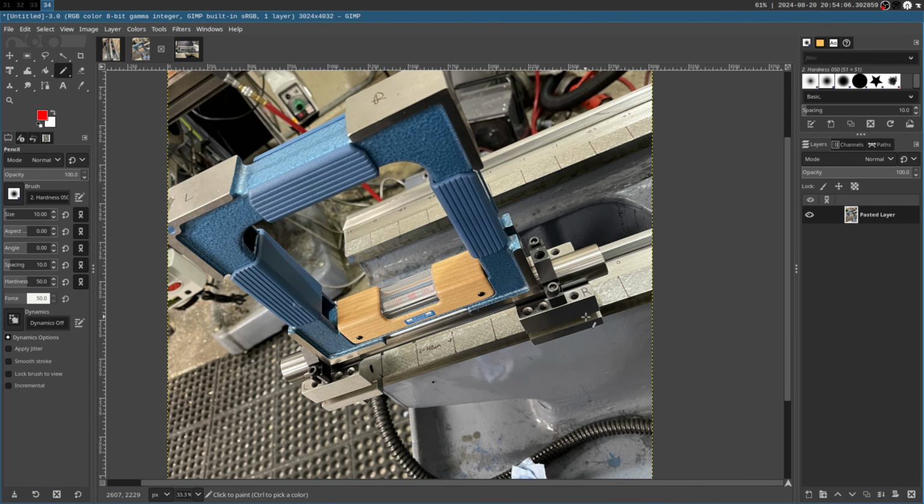Okay, anyway, so this is the little dumbbell that I built, and then what I do is I take the dumbbell and I set the level on top of it. You can see that I've denoted the left and right of the dumbbell and of the level. This makes sure that even if there is slope in the dumbbell, let's say this side was lower than the other and this is always sloping down, the way that I'm setting my level on there and the way that I'm getting these measurements means that that doesn't matter, right?